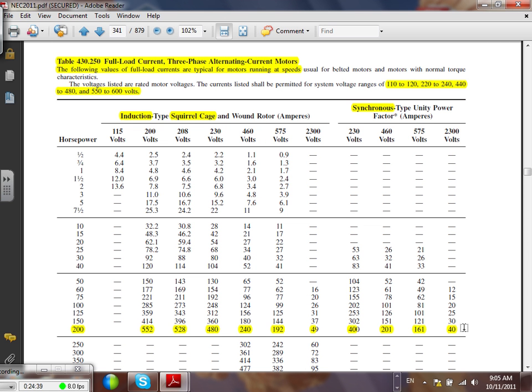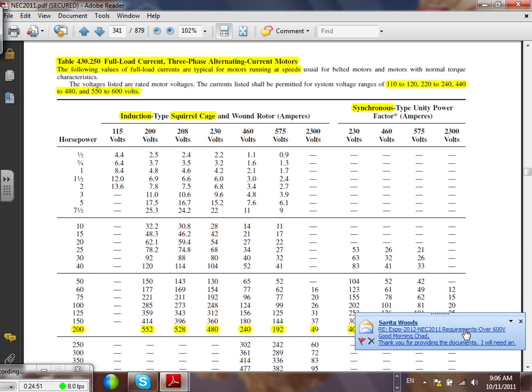What's the difference between the overload and the overcurrent protection? Good point. Overload protects you from overload. Here's what overload is. Suppose you have a pump that's supposed to pump water up to a 2-story building, and you single-handedly, Chris, decided to install it into a 4-story building. You're overloading that baby. You're not short-circuiting it, but it's working hard. Two things are going to happen. Either you protect it from overload, or you're going to see smoke after 2-3 hours of running.